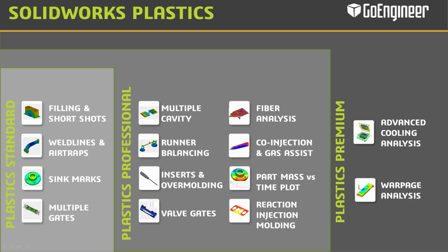If you go up the next step to Plastics Professional, you get everything within Standard, but it's designed more for your mold builders or tool designers. So you work with multiple cavity molds, family tooling. It's got a very powerful runner balancing tool, so you can make sure you've got a balanced shot and pressures between unlike parts of different sizes.